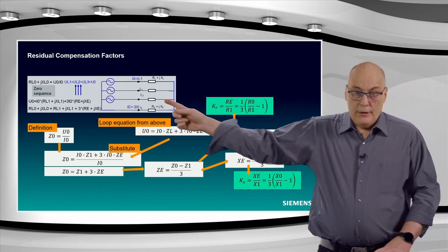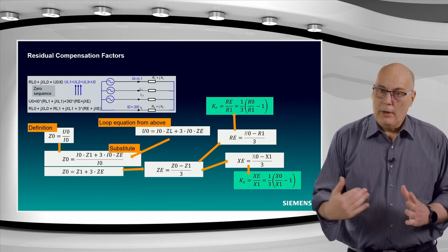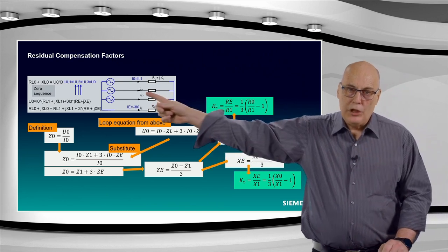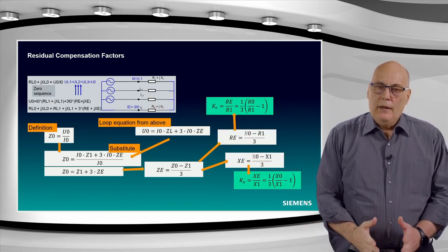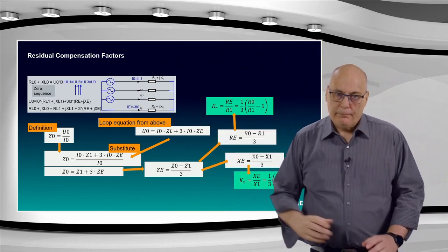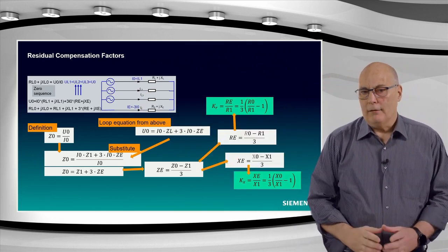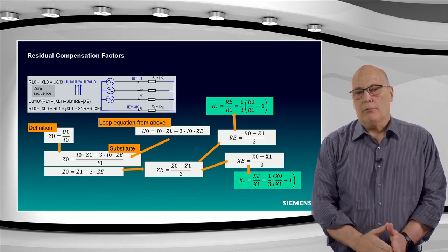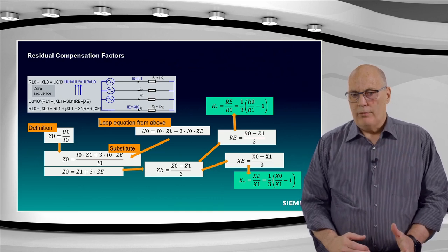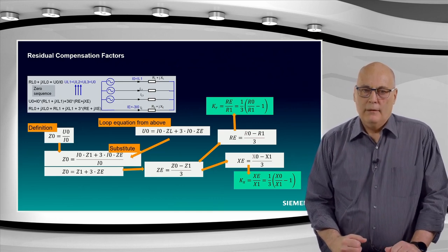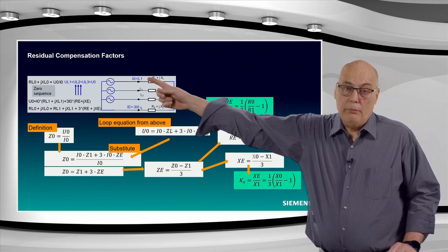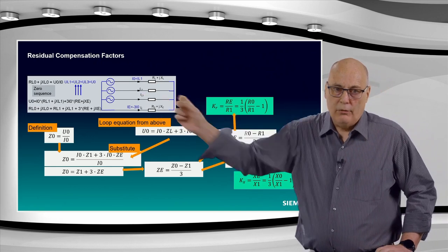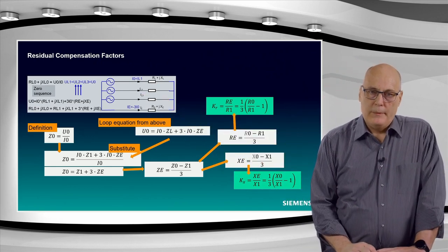So what am I trying to show in this diagram? In this diagram here, I connect my three phases with a short circuit at the end of the line, so to speak, and I inject at the beginning 3 voltages, and the 3 voltages I inject are those 3 blue arrows. They are exactly in phase and identical. So in that case, what voltage is that? That is the zero sequence voltage by definition. But the zero sequence voltage means that it is exactly the same in all 3 phases, magnitude and angle. That is a zero sequence voltage. What you could do in this case, you could make a short circuit here because the voltage there is identical and replace that injected voltage with a single U0 zero sequence.